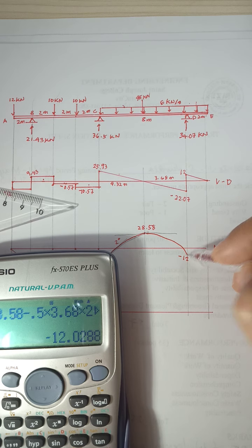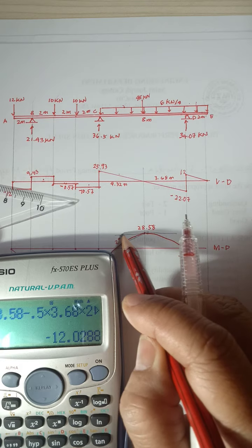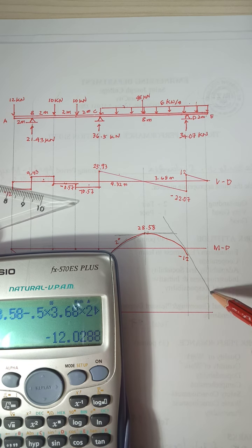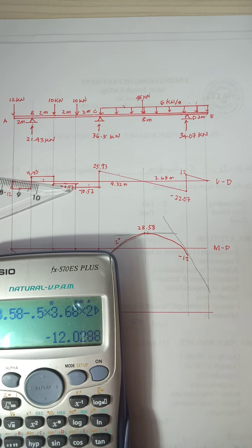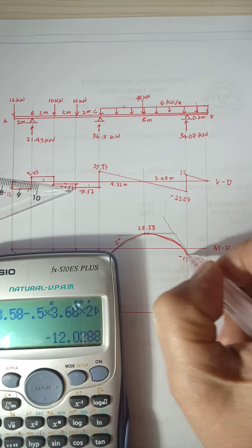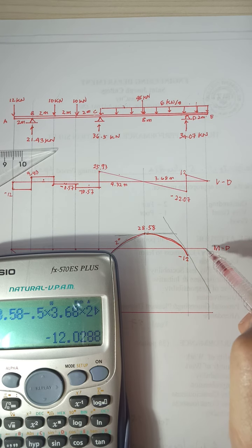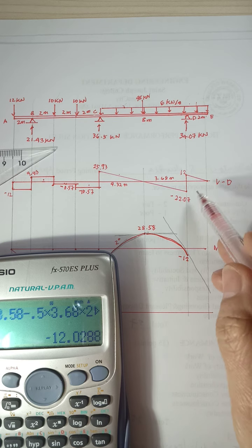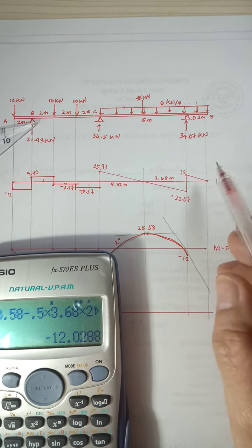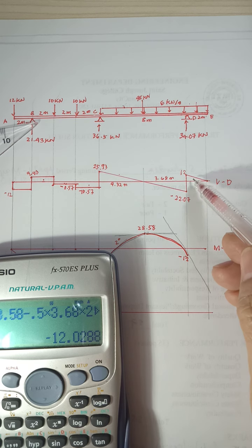So your curve now, this is 0, so you also start at 0, and then the slope is negative, so the line goes to the left. So its slope is like a tangent, which is your negative 12. Okay. Your moment at the end of the beam is the sum of the shears to the left of that section. Okay, you already have a value here at D, so you just add it.